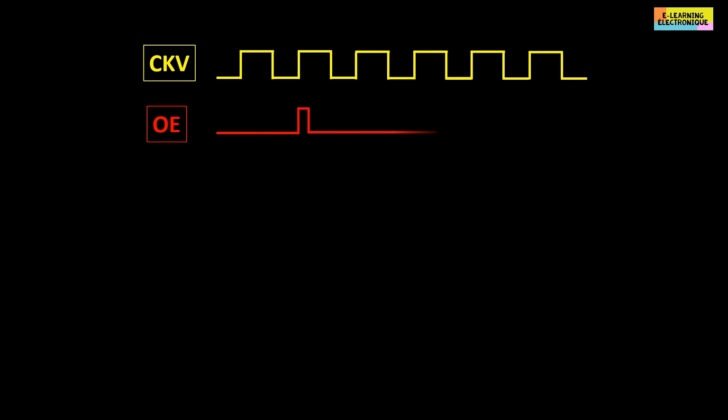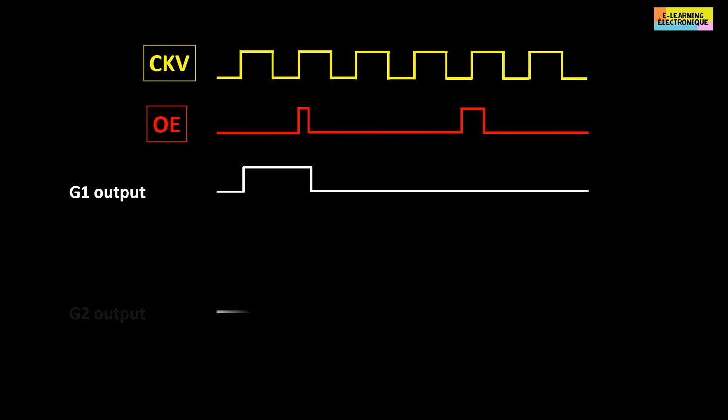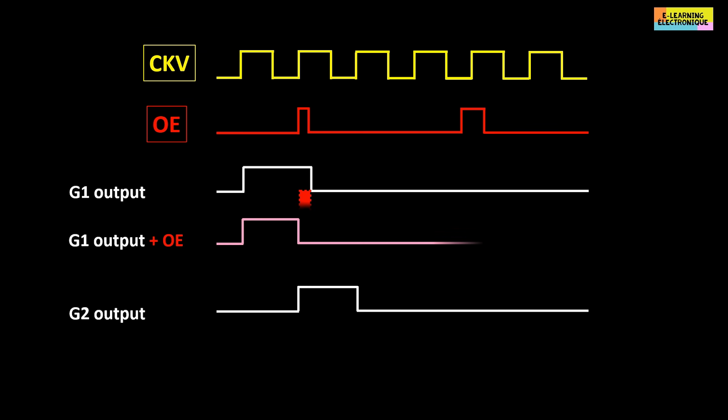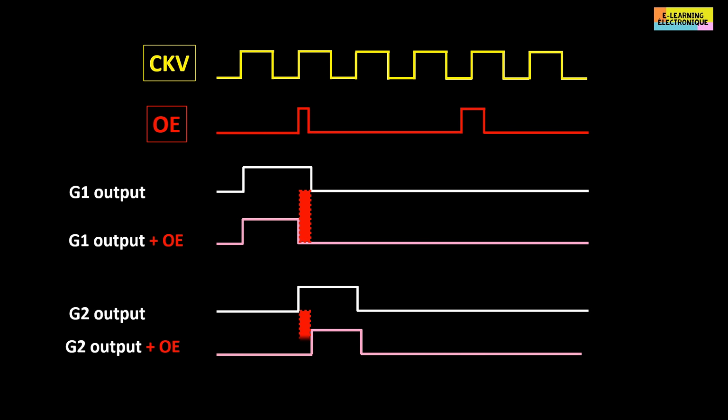To correct this crosstalk problem, we introduced the OE signal, for output enable. When this signal is at high level, it stops all the lines that are active. When unfortunately the operating time of two lines overlap, OE allows to block this zone. This prevents the data from being misdirected. This is equivalent to controlling the operating time of each line. The width of the OE pulse is variable and only acts on the lines that are active at the same time.